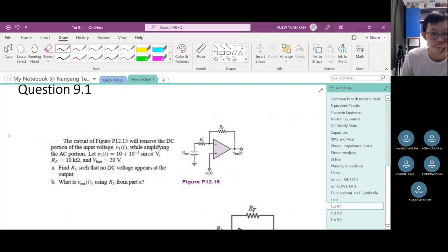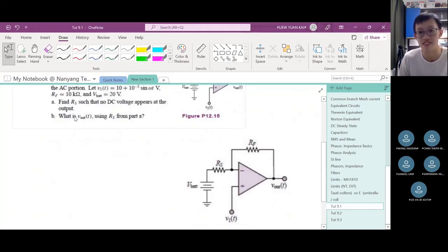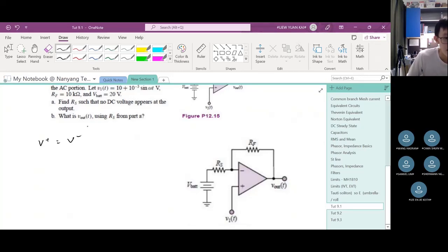Okay, so to cut to the chase, all the nitty-gritty from op-amp, what you have to know at the end of the day is literally 3 things that I'm about to tell you. Take these 3 things with you to the grave, and literally 90% of what you should know about op-amp will be done. Whenever you see the op-amp, immediately write this down: V plus equals V minus.